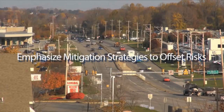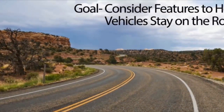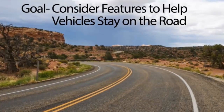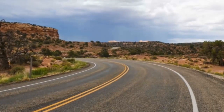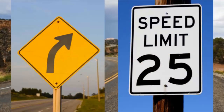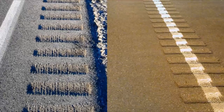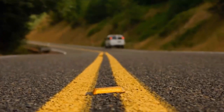For example, what mitigation strategies could you consider to address a sharp, substandard curve ahead? In this situation, your goal is to consider features proven to help vehicles stay on the road to mitigate the risk of building a substandard curve. In this example, you could address this situation by including mitigation techniques such as the installation of warning signs or speed plaques, widening the roadway or shoulders, installing rumble stripes, adding super elevation, or incorporating a skid-resistant high-friction pavement surface.